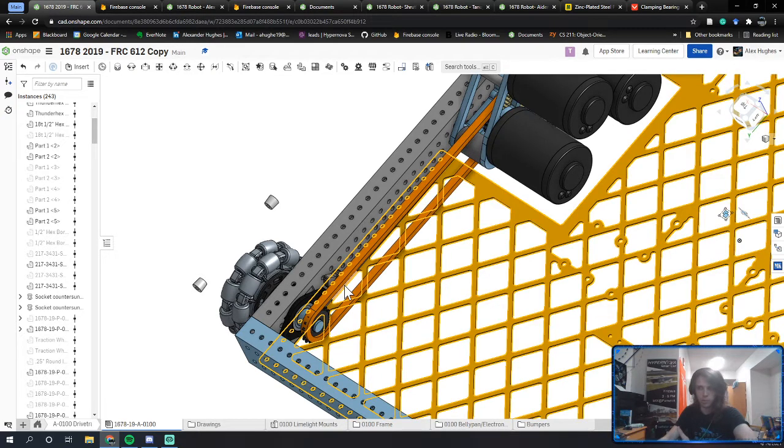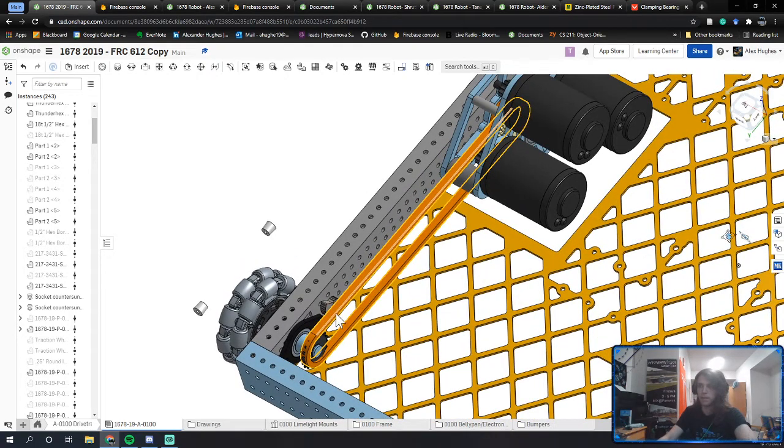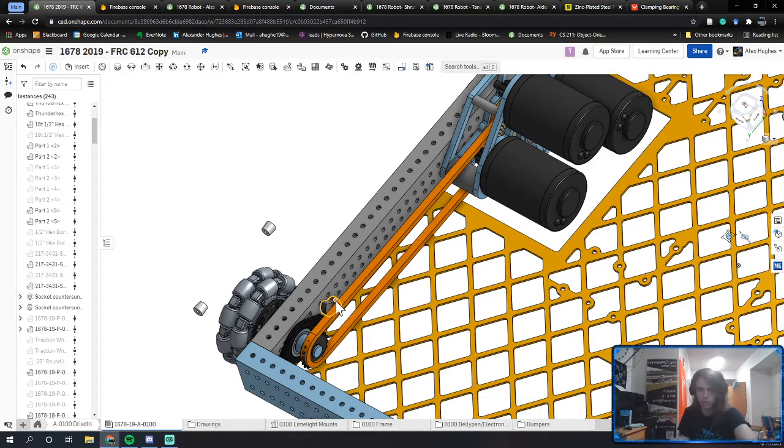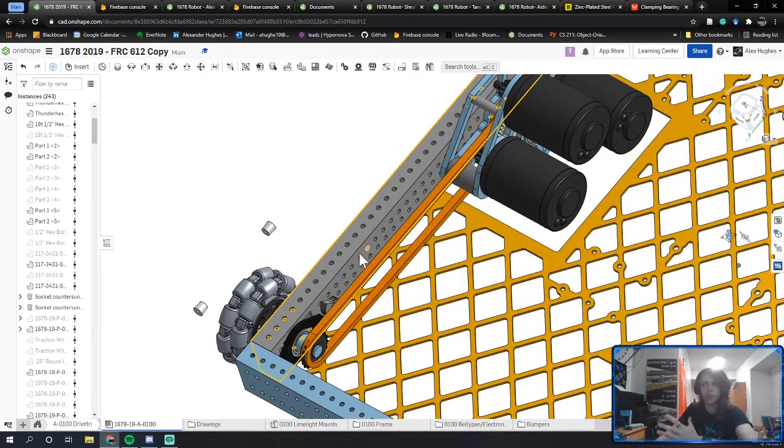It doesn't matter which one you use. Chains tend to stretch more than belts, which is part of the reason I prefer belts. Basically, the linkages between your chains start to wear out and stretch over time. Each linkage will only stretch by maybe a hundredth of an inch, but the longer chain you have and the more linkages you have, the more your chain will stretch.